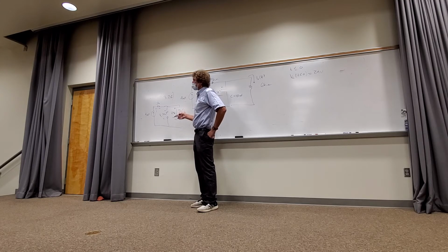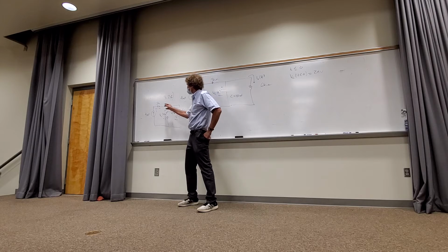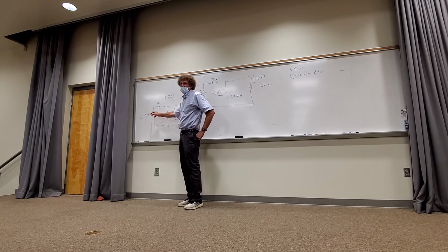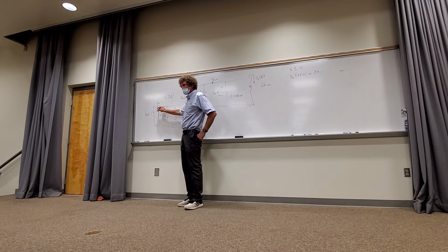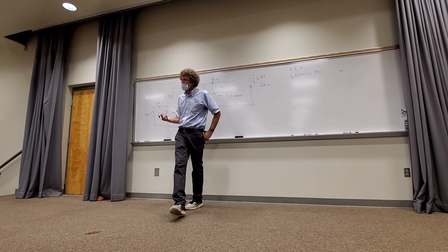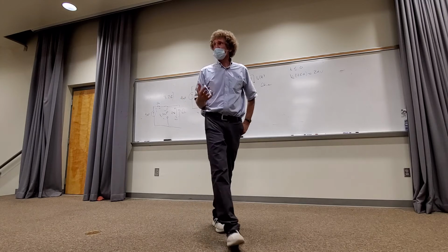Well, okay. Here's what he said. He said, what if we do a source transfer? Yeah, if you want to, you could do it that way, but what do you find? You get 12 volts, right? In series with 3K, it's going to end up with the same result. You don't even need to fuss with that. Don't make more work for yourself. I'll give you plenty.